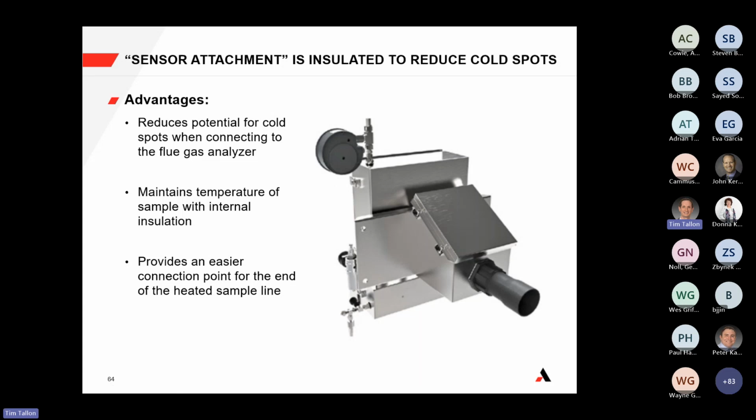Okay, I'd like to point out that we use the boots to seal up around the heated sample line, and that keeps the heated sample line from being compromised by rain or snow, and it just seals up very well. So we use them both on this end and on the probe end.